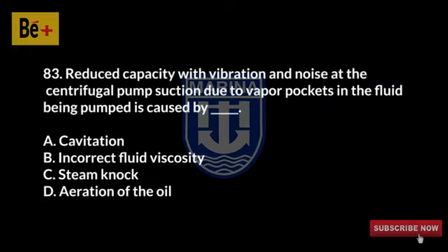Reduced capacity with vibration and noise at the centrifugal pump suction due to vapor pockets in the fluid being pumped is caused by: A. Cavitation, B. Incorrect fluid viscosity, C. Steam knock, D. Aeration of the oil.